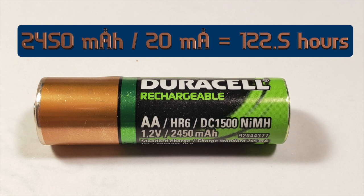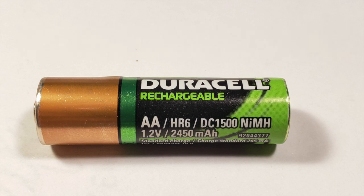Of course, to get the 5 volts that we would need, you'd need 3 of these batteries. You take the 2,450 milliamp hours, and it would still be the same amount of time, because all the batteries are being drained at the same rate. You don't drain one and then drain another and then drain another. But if you had the 4.5 or the 5 volts coming off of these 3 batteries, you would have enough voltage to be able to make that work properly.